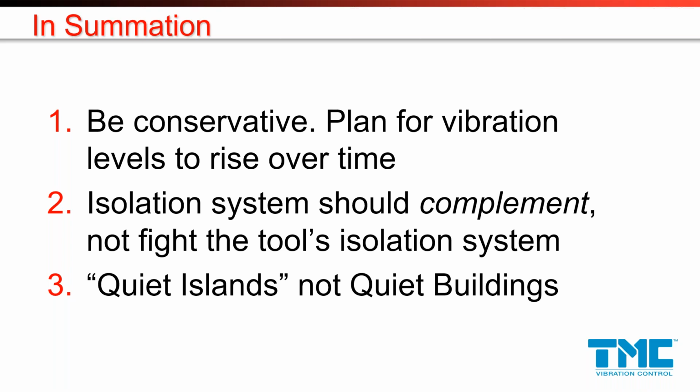Well, everything applies that we talked about. So what you're going to see in a higher level building is you're going to see higher levels of vibration, and you're going to see it at lower frequencies, right? When you go up to extremely tall buildings, you're going to have the building sway be a period of, good grief, I don't know, 10 seconds or maybe more. And that is such a low frequency that it's outside of the bandwidth of the active systems and really outside of the vibration criteria of the instrument. But you're not going to see ultra-sensitive instruments installed in very, very high levels in floors.